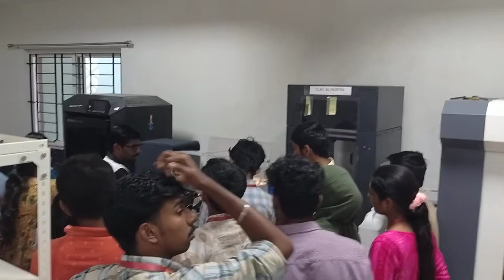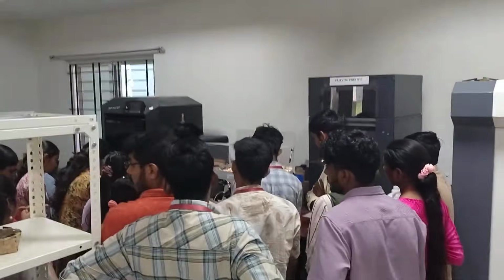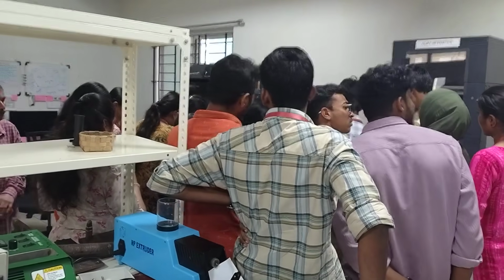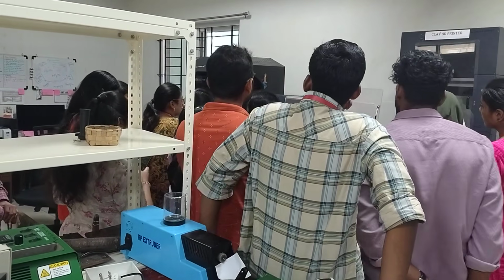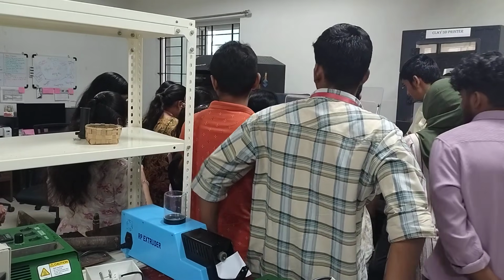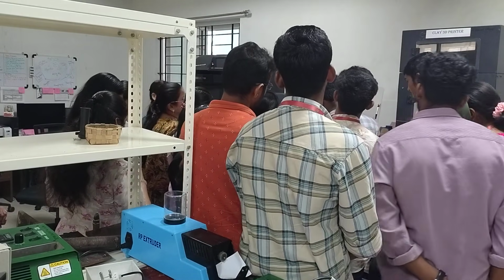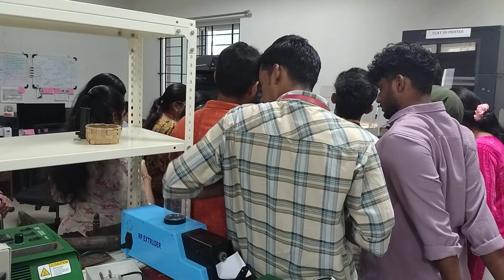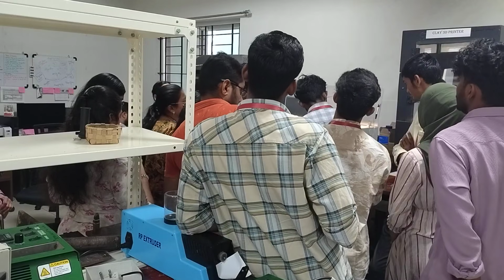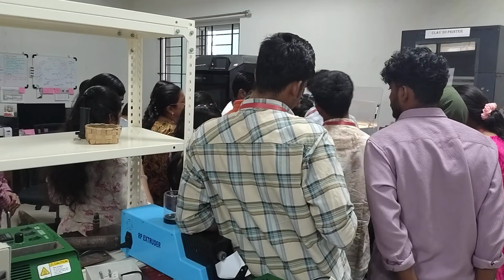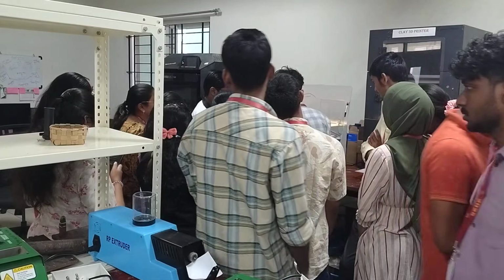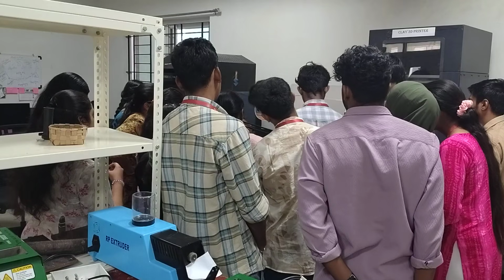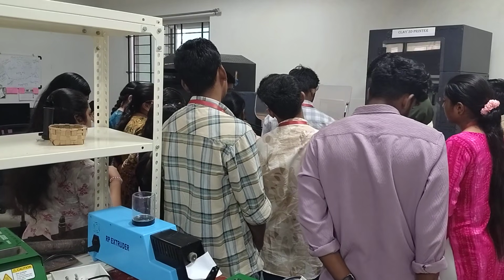Okay, since the extrusion has not happened, I'll click on retry. Yes. So now the filament is coming all the way and it goes to normal. For this you have to be a little bit ready and cautious that when it starts coming out, suddenly you have to click on stop. A kind of tick sound will start coming. Yes, stop. So now our filament is coming from here. So our fiber is loaded.